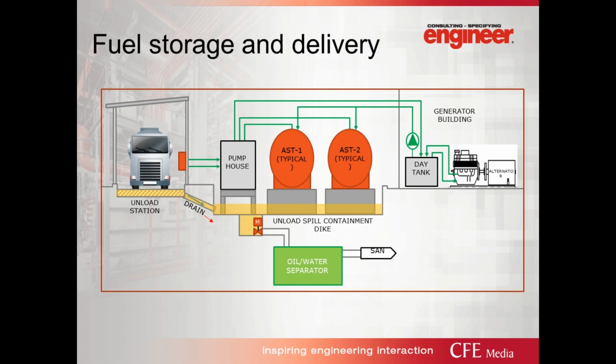The other thing that is outside of sort of electrical design that we have to worry about a lot is the practicality of refilling these generators. A tanker truck can only hold so many gallons. And if you have a large generator fleet and a lot of bulk fuel storage that you need to replenish, if you have 96 hours of uptime or something like that, you need to understand how many trucks do I need, how will they get in and around the site without bottlenecking, how long will it take, and does my service provider actually have the fleet to meet what it is that I need?